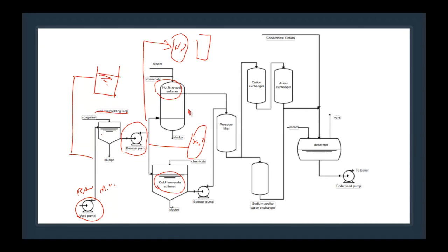Usually if we're going to use H2Z or sodium zeolite on its own, then we would have a system where the raw water makeup might be safe from the city water or municipal water. For example, here at SAIT, our raw water is hard, yes, but it's not super duper hard, so we can put it right into a sodium zeolite softener.